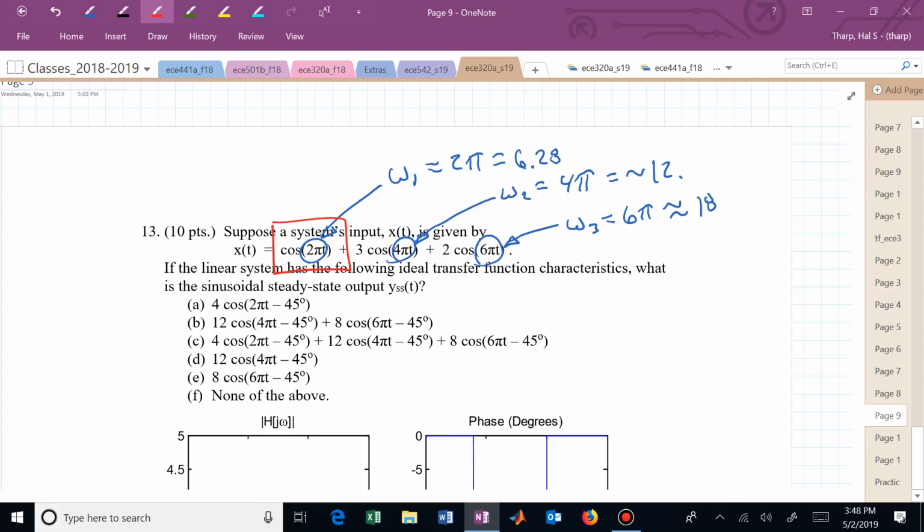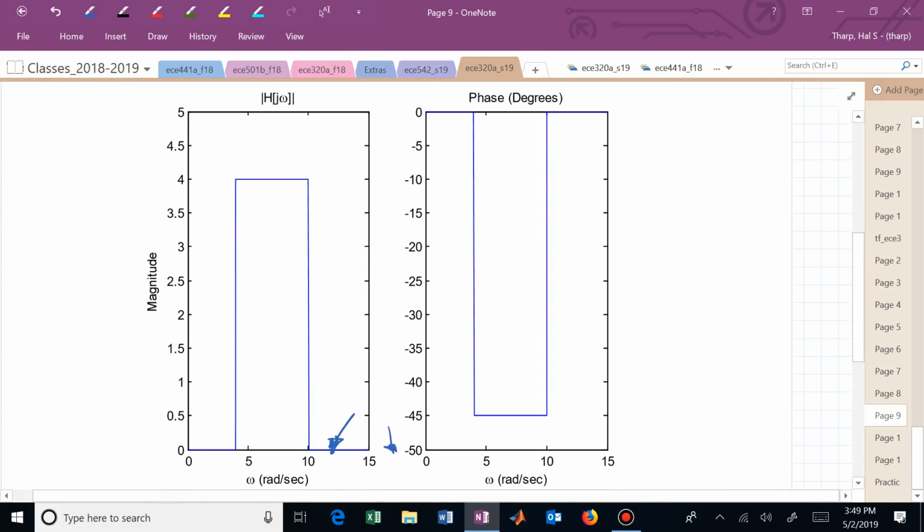So we've already figured out probably, unless it's none of the above. But if we now inject a cosine at 2 pi into a linear system, we know y is going to be shaking at 2 pi. But we also know that the system might influence the amplitude and the angle, or the phase. And these two plots tell us how that magnitude and angle are introduced from this system. What's the amplification going through this system at 2 pi?